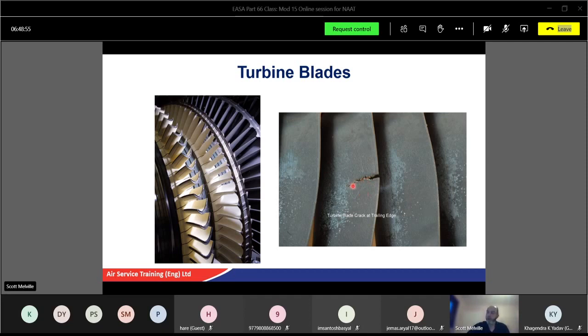Because what's going to happen? Well, that's a stress point. That blade comes off. Now, if that's an HP turbine, that blade will snap off. And if it's a triple spool, it will break the IP turbine, then that will break, and that will break the LP turbine. So a lot of damage could potentially happen. If it's an LP turbine, bad enough, it's still an engine rejection. Again, you might be able to access the HP and IP from borescope inspection, the endoscope.